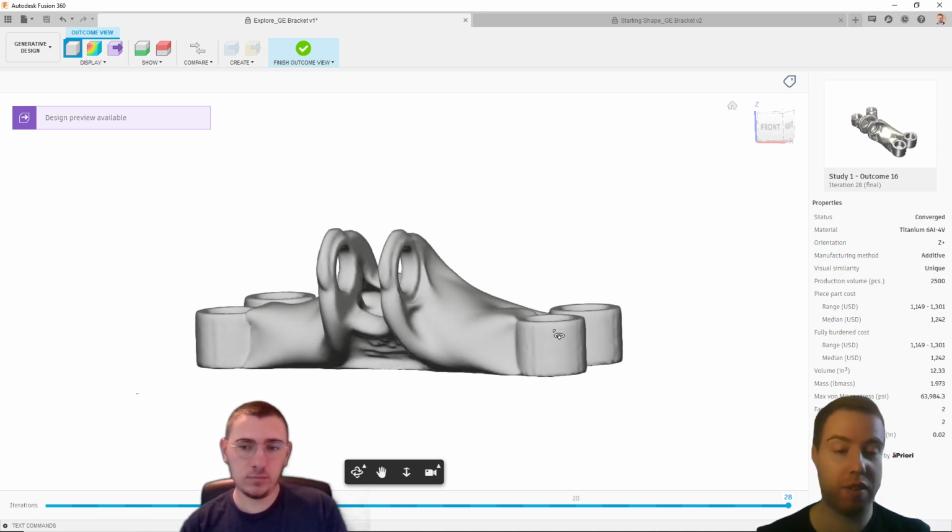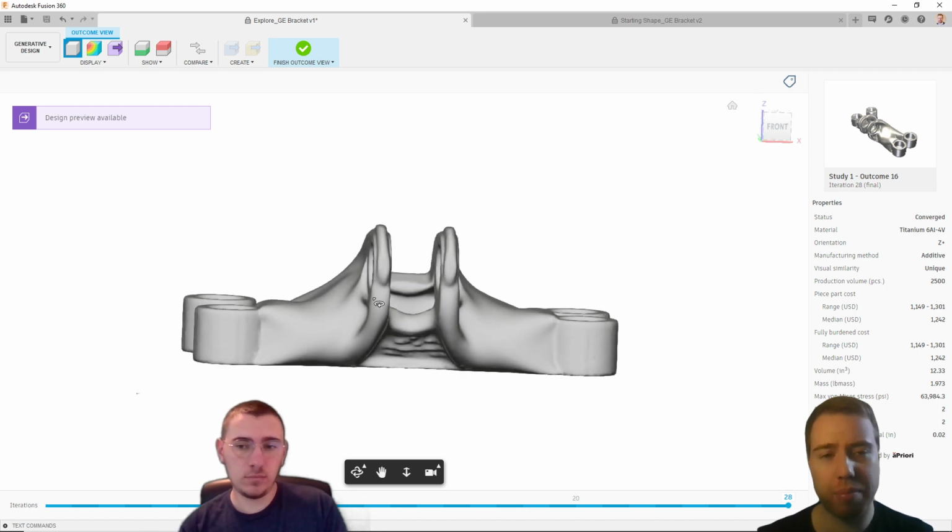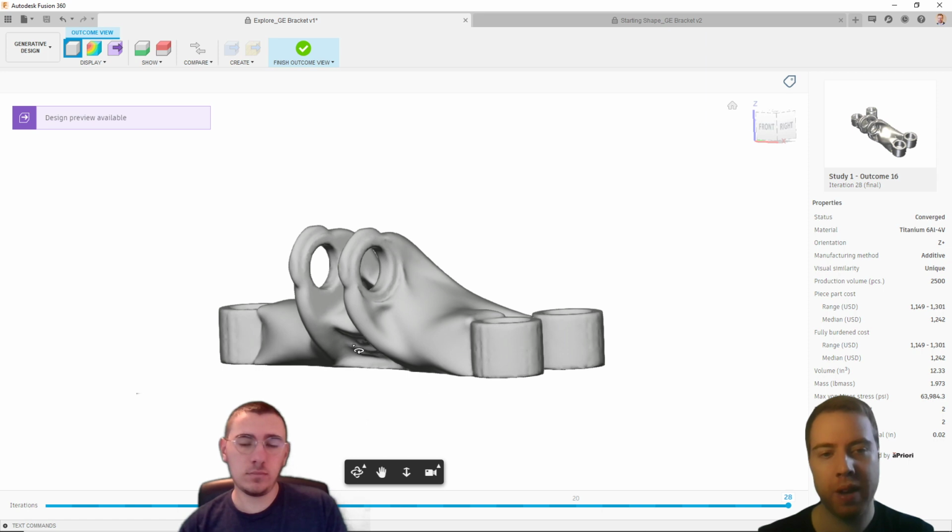After we've manufactured this part, we then need to manually remove that support material, and this is often done just with hand tools. So you can imagine that process can take a long time and really add to the cost of these components. If we can design parts which require as few supports as possible, that's a big advantage, and that's exactly what generative design is looking to do.